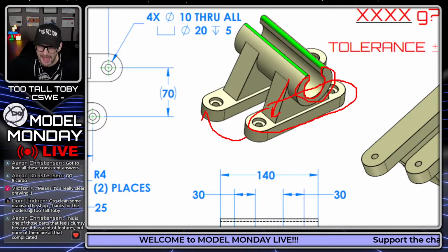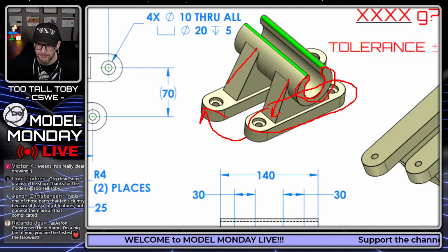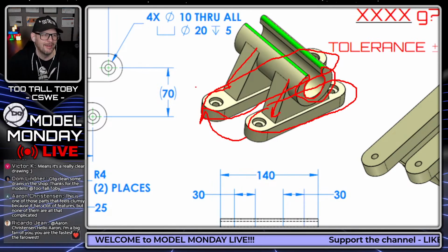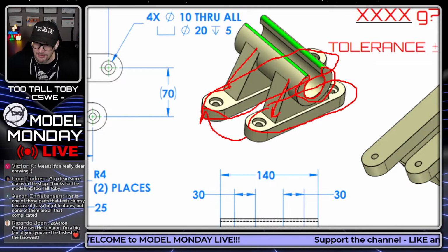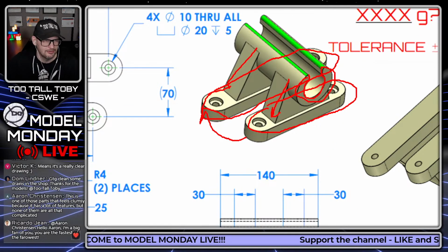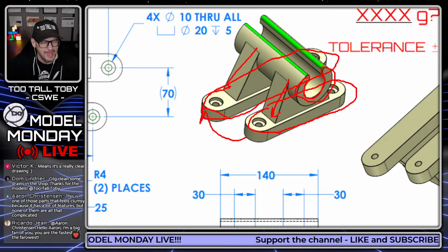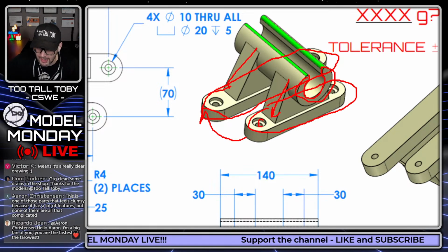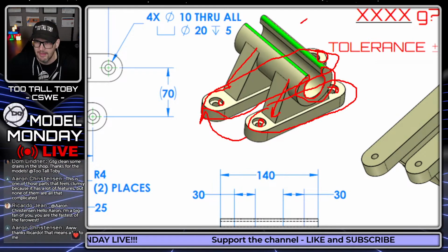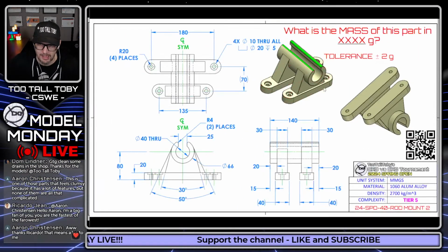We're going to create a pattern of this leg, and we're going to use vary instance on the pattern. Kind of a cool little feature if you know advanced patterning. We learn about that in the advanced part design or part techniques in Toby's SolidWorks training classes. Then we'll finish off by going through and adding in these counter bores using Hole Wizard, because that should just be a simple click, click, click, click. And then we've got to remember to add that fillet at the very end.